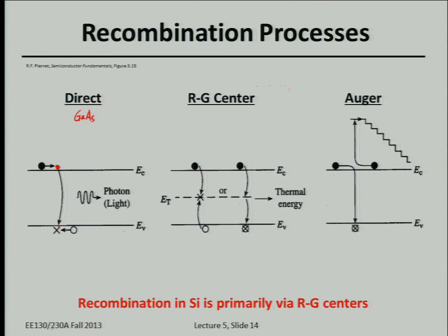And the second thing is the RG center, trap assisted recombination. Basically, electrons first make a connection here, so they just stay at the trap levels and wait for a better time to get some more energy, more velocity change, and then from the recombination with the holes jump from the valence band.